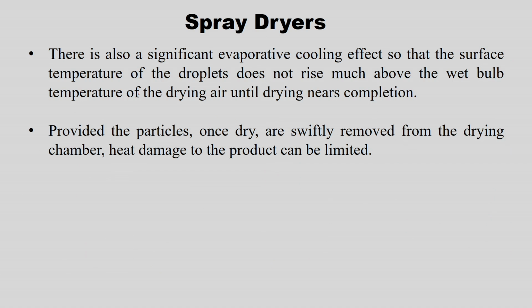There is also a significant evaporative cooling effect, so that the surface temperature of the droplets does not rise much above the wet bulb temperature of the drying air until drying nears completion. So total drying takes place at a temperature less than the wet bulb temperature of the drying air, because the droplets do not increase in temperature, right. Due to the evaporative cooling effect, the droplet temperature does not rise, which always remains less than the wet bulb temperature of the drying air.